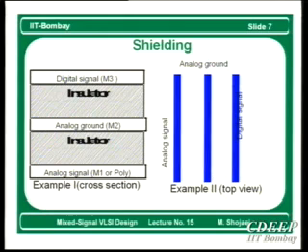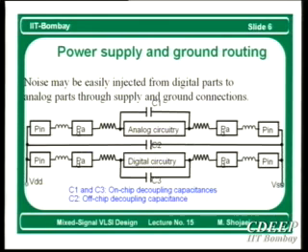Essentially, all supply lines, VSS and VDD, should be very wide compared to signals, because they should have a very small resistance. And high capacitance is better, right? We like to have a very high capacitance. In fact, if you use very wide lines, you are increasing C1 and C2, which is good.